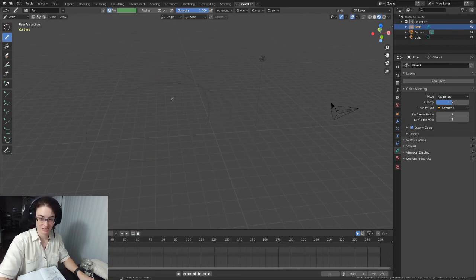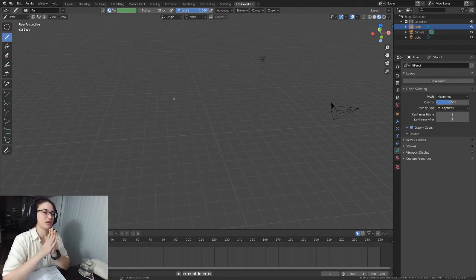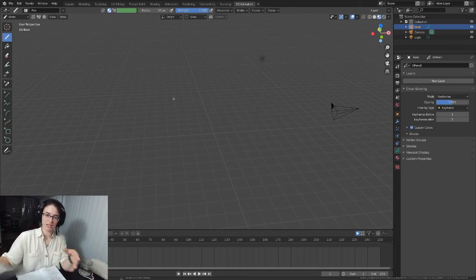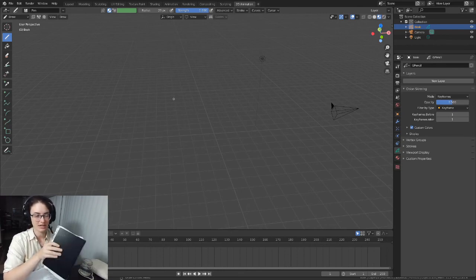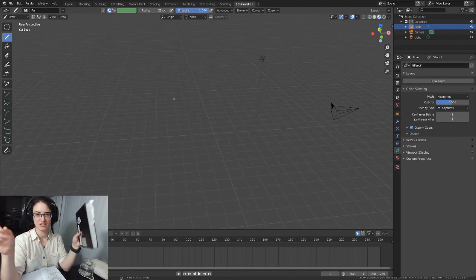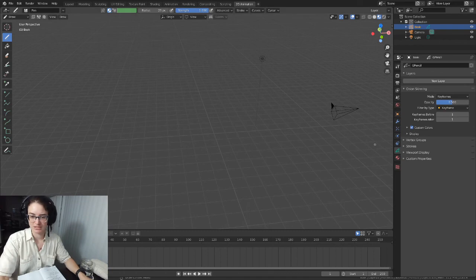Let's put a material on it. While we're working in this, it's going to be a little different workflow than when we were modeling with meshes and primitives, because there we made our full model with a cube, and then at the very end we put textures on. For this, it's handy to do materials as you're working, otherwise you're going to have a 2D wireframe filling up your view and it can get a little overwhelming.